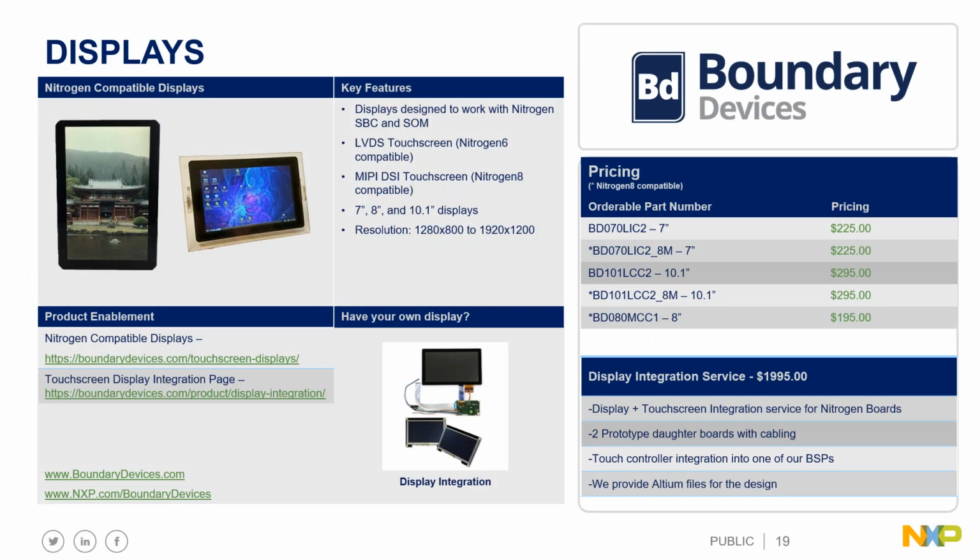So from a display perspective, we've enabled 3 different types of displays. 2 of these displays are 7-inch and 10-inch, or actually LVDS displays. The i.MX 8M Mini only supports MIPI DSI output. So unfortunately, in the industrial market, a lot of these displays are LVDS. Gary will dive a little bit deeper into this, but we have a MIPI to LVDS conversion that goes on there to drive that. We also have a native MIPI 8-inch display. And again, the purpose of these displays is to give customers something out of the box that works immediately with the board. They can start their development, they can start their evaluation.